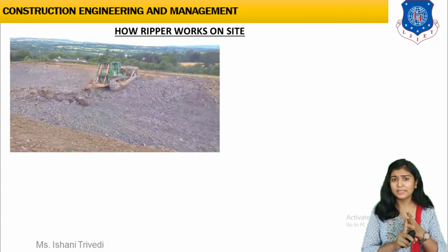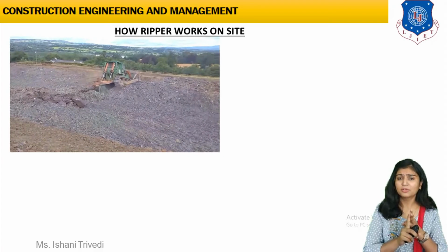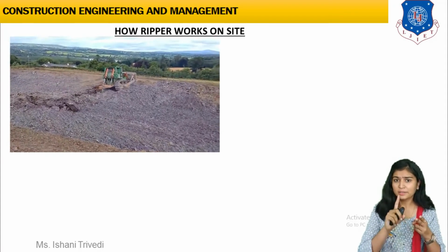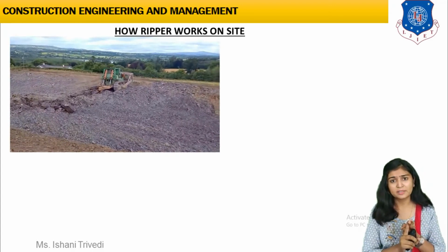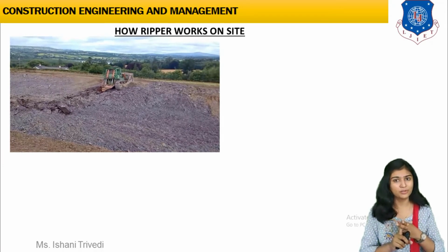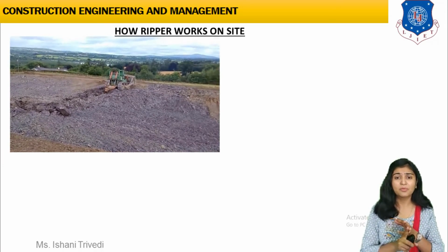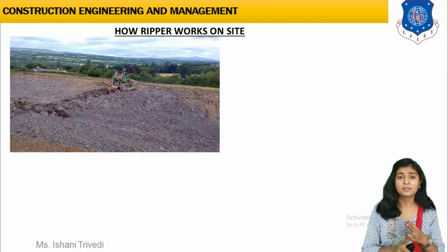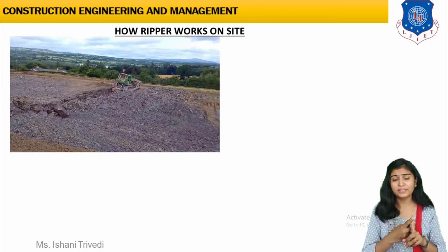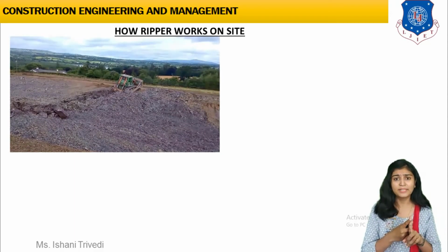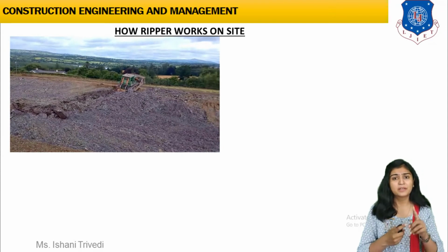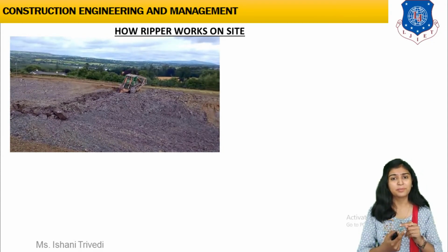It is an obvious thing that when you are dealing with soil that has hard boulders and rocks, the crawler mounted is the proper choice for us. We have already discussed crawler mounted and wheel mounted. Then you can see the mounted thing is your ripper. It has only one tooth, made up of sharp edges, sharp blades. So you can see how it is moving forward and backward and performing the ripping work.